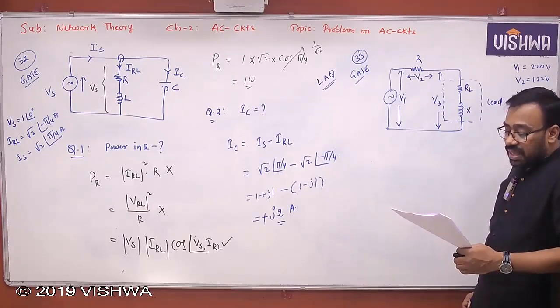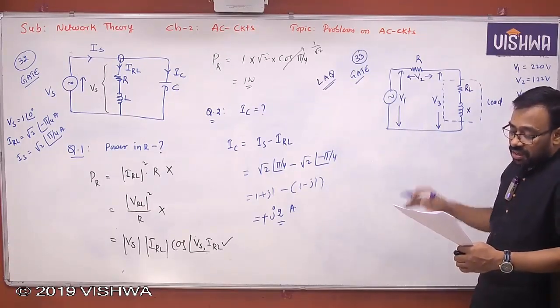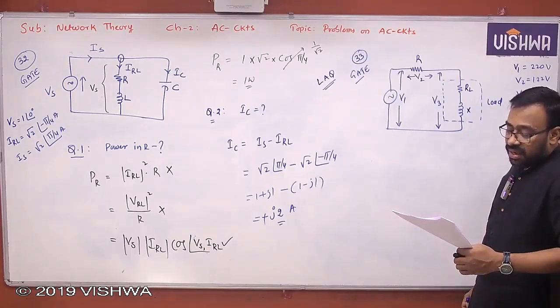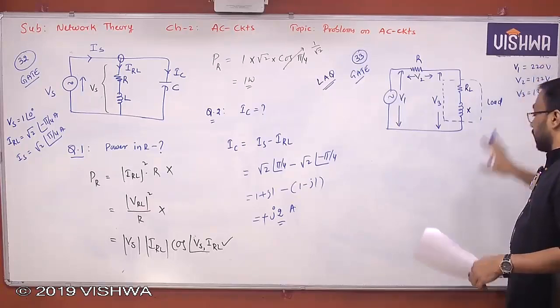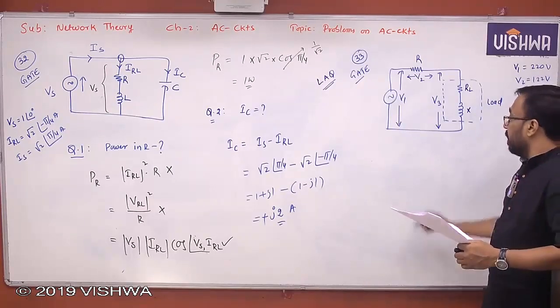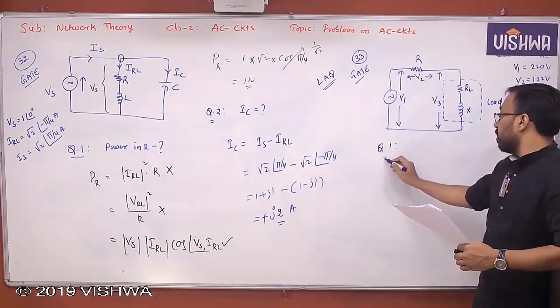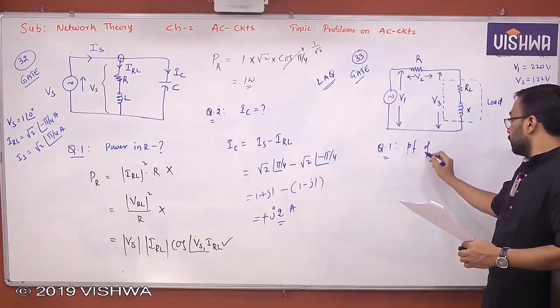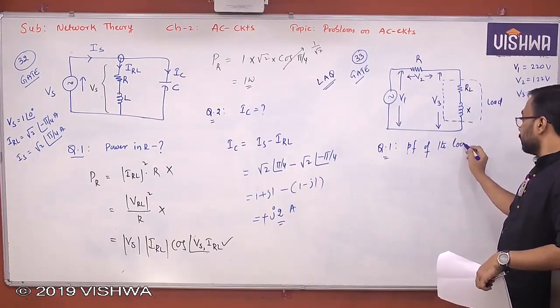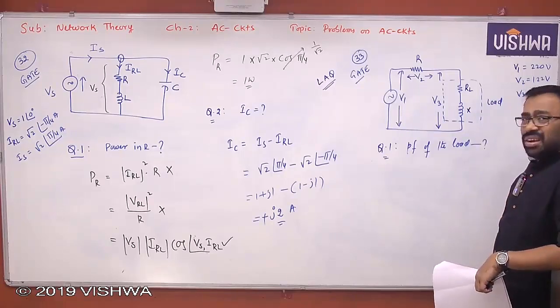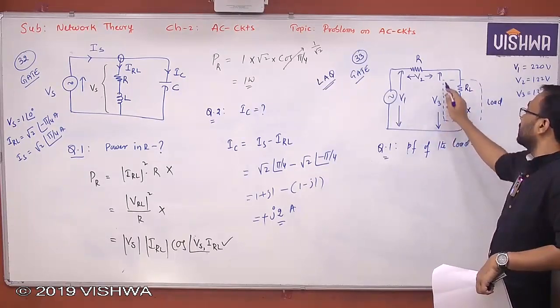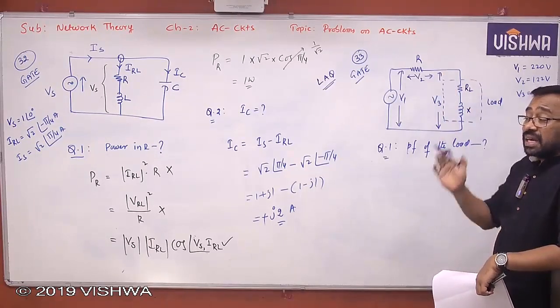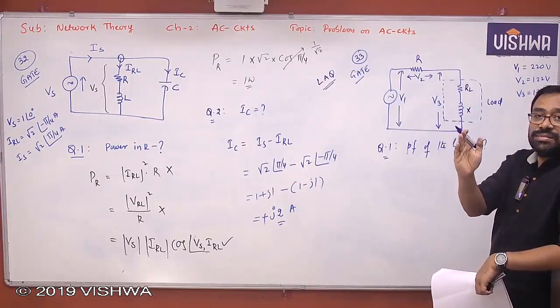Read that here. In the circuit shown, the 3 voltmeter readings are V1, V2, V3, with some values given. Then the power factor of the load is what? I think all of you remember I have explained the phasor diagram concept when V1, V2, V3 are given, when a practical inductor is connected in series with a resistor, or a practical capacitor is connected parallel to a resistor.